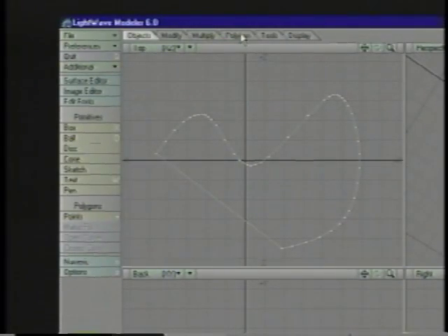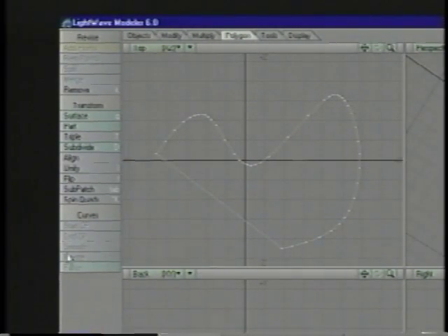And again, it's flipped, so I'm going to rotate this guy around. And you can see the curve that I had drawn out is now frozen into a polygon. That freeze tool is right here under the polygon menu, under curves. It's ghosted out right now because I already recreated the polygon, but if I undo my polygon creation, you'll see that I just have the curve there now, and I have that freeze option available to me. And if I click on that, it'll freeze that.